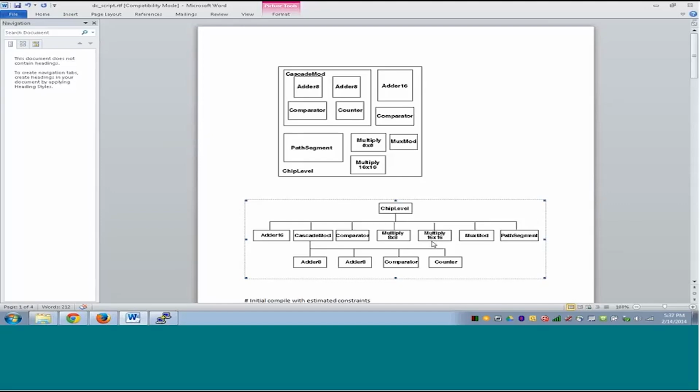But in this case you have to make sure that your hierarchical design's input and output delays are very good, because obviously manually you will not be able to do a job as good as Design Compiler. So now you know all three ways to do synthesis: top down, bottom up using characterize and write script, and bottom up using black box.